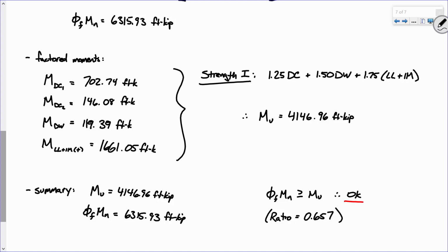Save on money, okay? And the answer is there's more going on, okay? We haven't looked at fatigue. We haven't looked at the constructability check. And I've mentioned this before, there are many cases where the worst loading condition that a bridge sees is while it's being constructed, okay? That's very possible, okay? We're not finished yet. But so far, the positive bending region's doing fine, okay?